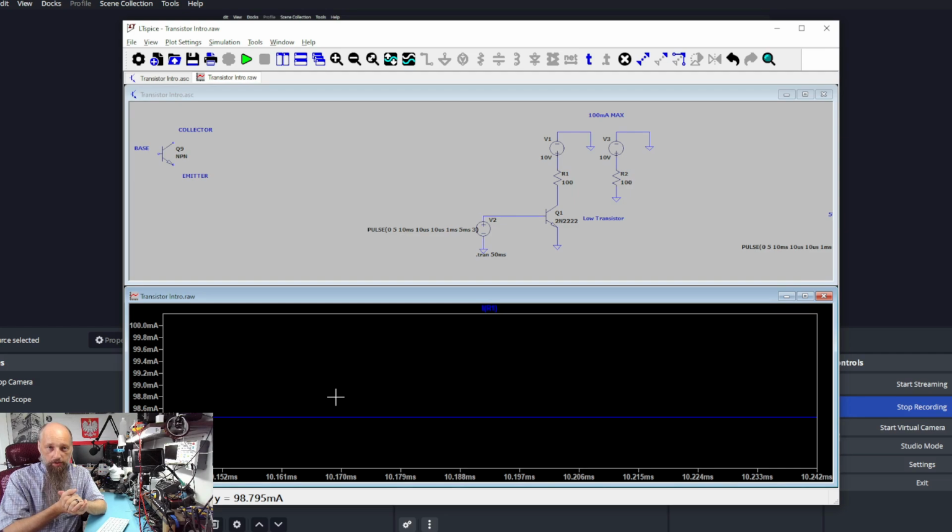This property could be written in the data sheet of the transistor. This particular one does not, because it's not a power transistor. Usually on the power transistors, that property is important because you're going to be driving big loads. There's going to be a lot of current. So the higher the resistance, the more power or heat will dissipate on the transistor. For that, you need to adjust and find proper heat sinks or proper way of removing that heat. That will also create a limit for your transistor.